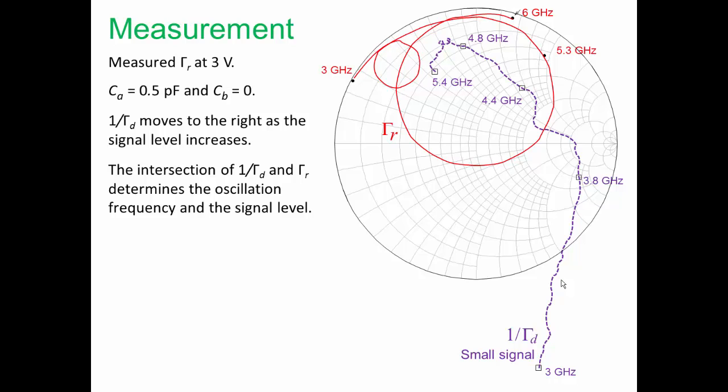So we're taking our active network, we're connecting a 50 ohm cable to our SMA connector, so we're loading the active device by 50 ohms, and this device does not oscillate if it's loaded by 50 ohms at that resonator connection. We're doing measurements at fairly small signals, could be in the tens of microwatts range. We're not driving the transistor so strongly that we're seeing nonlinear effects.